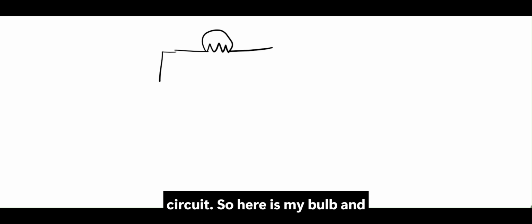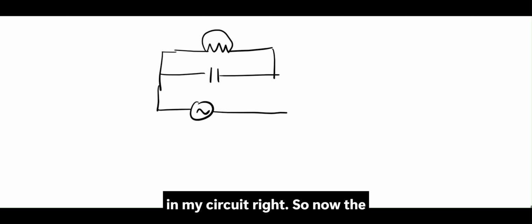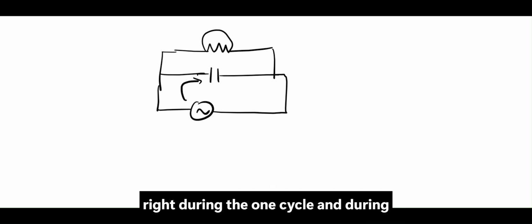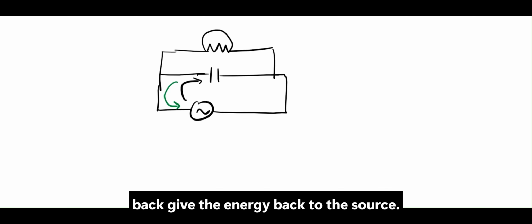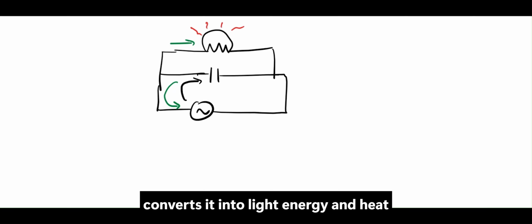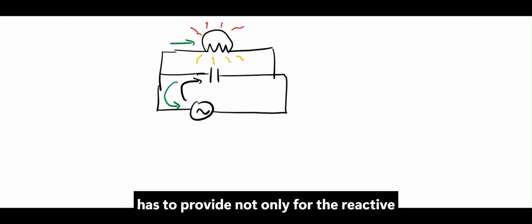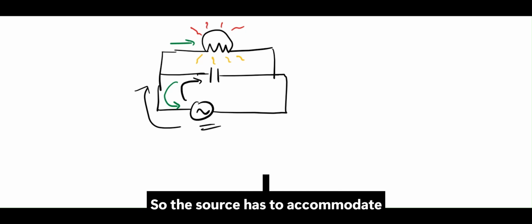So I'll just redraw my original circuit. Here is my bulb, and I have added a capacitive reactive element, and I have an AC source in my circuit, right? Now the AC source charges my reactive element during one cycle, and during the discharge cycle the reactive element gives the energy back to the source. So there is always an oscillation going on, and a part of the energy provided by the source goes to the load, which converts it into light energy and heat energy as well, right? So now my source has to provide not only for the reactive element but also for the load, so the source has to accommodate for both, right?